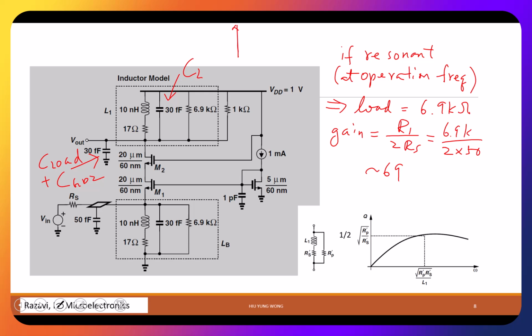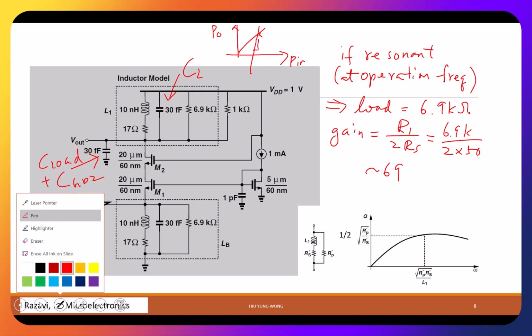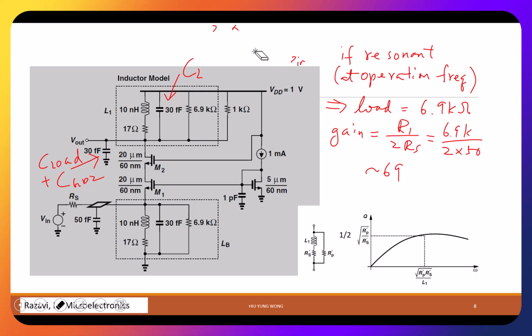If you look at the output power versus input power, for the base tone, or first harmonic, you may have something like this. And then if you go to the third harmonic, it has a deeper slope. Now, when your power is low, this is in log scale, so you can ignore it. But once you reach a certain power, it becomes larger than your original frequency power. So there's something called, what, I forgot the name. What do you remember? IP3, what's that?